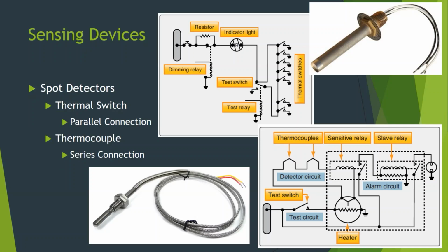So now the newer versions wire each switch back, and you go into the maintenance computer. You can look in your maintenance computer, and it will tell you switch number, right-hand number 2 is the one that's triggering. Okay, I know exactly where that is. That's in the inboard section of the wing. It's the second switch. You can find it a lot easier. So for maintenance purposes, they've gone away from a lot of these parallel designs, and they're discretely wiring the switches so that you can troubleshoot them easier.